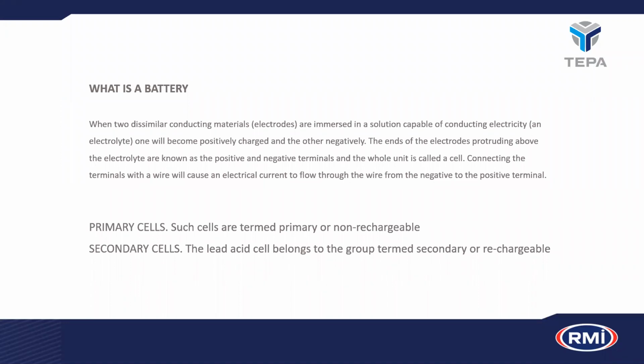The intelligent charging system then determines when the battery has reached its full capacity, and the alternator will either switch off charging current, or it will divert to the running of the vehicle so that it becomes a closed system.